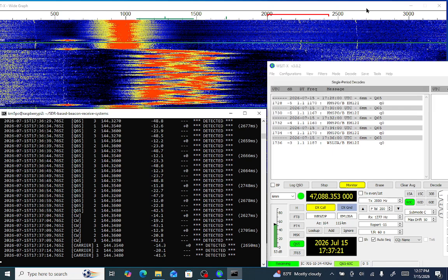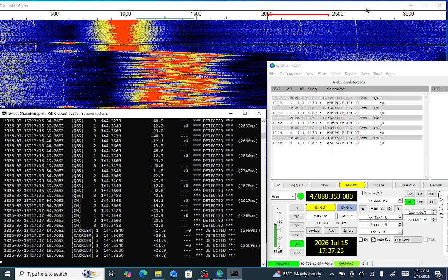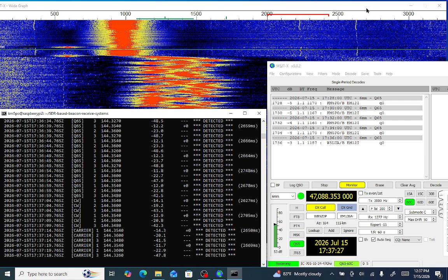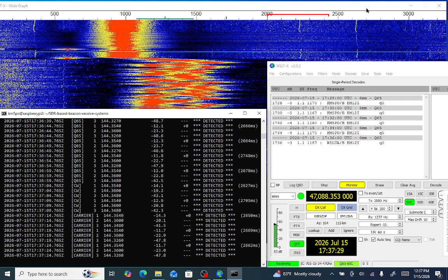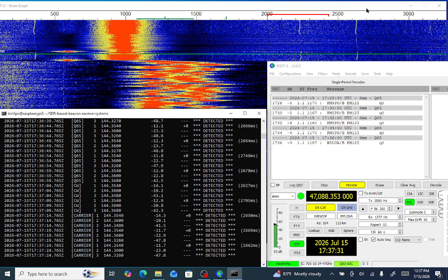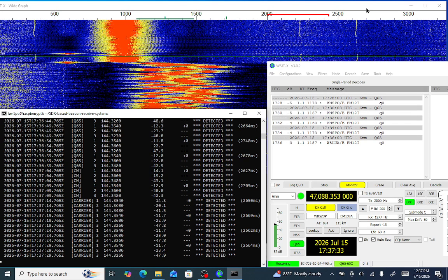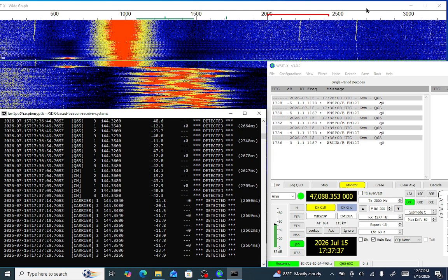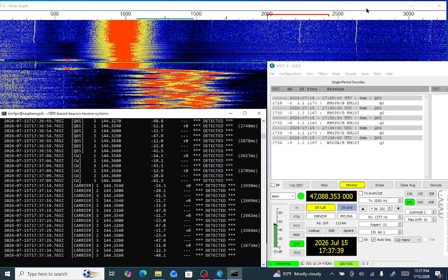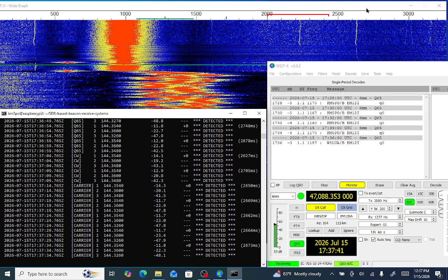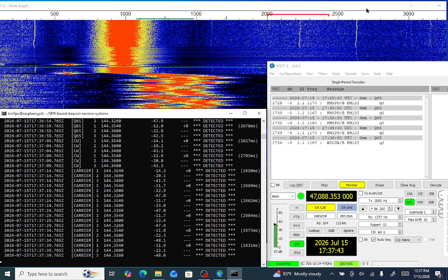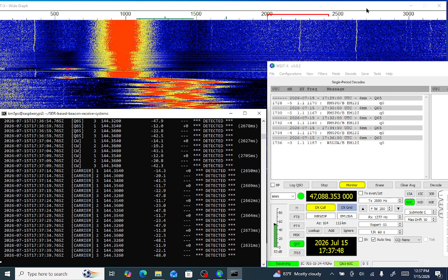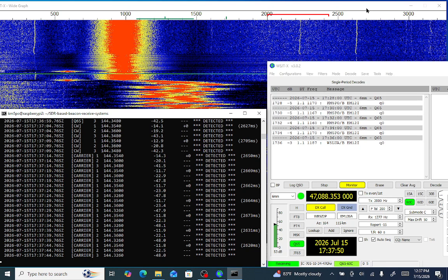So this is just to demonstrate that we've got a beacon monitor that can find 2 signals, and even a birdie there. We could probably just move our threshold around, but we'll need to know where the signal strengths are at the location where these are deployed, because we don't want the threshold to be set at such a high level that it can't find the signal that it's intended to find.